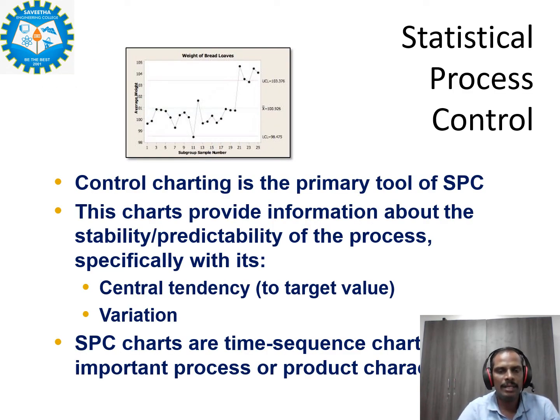This diagram is called a control chart. While the process is running, the collected data are plotted on the graph, and the variations between the upper control limit, the lower control limit, and the standard values specify whether the process is coming to the standard quality or variations are occurring.